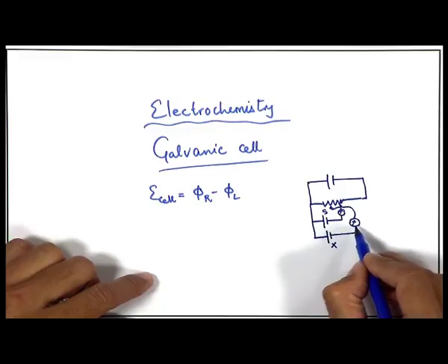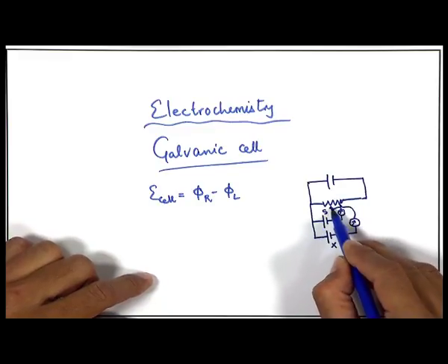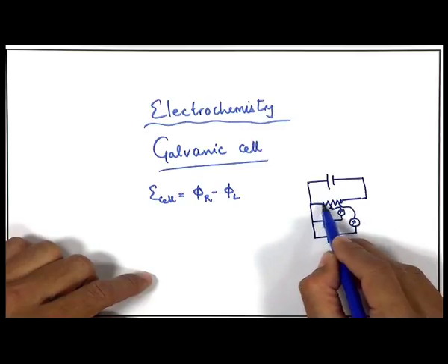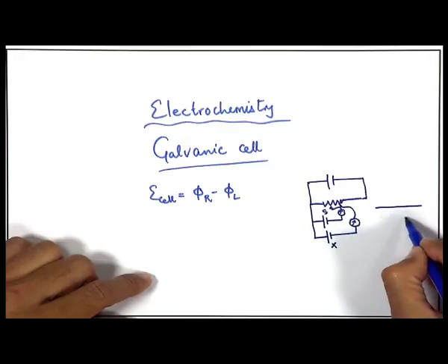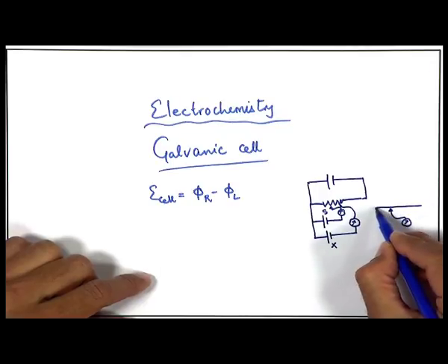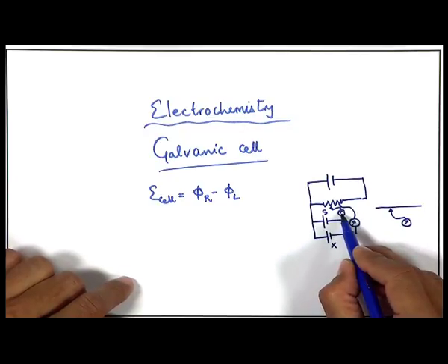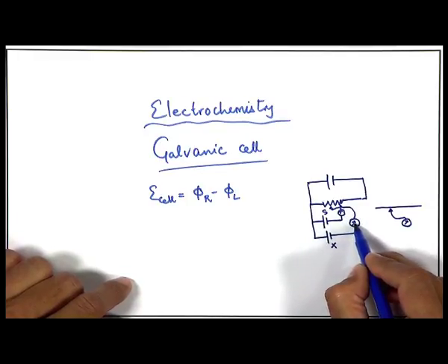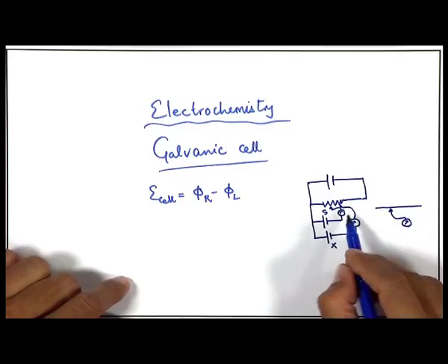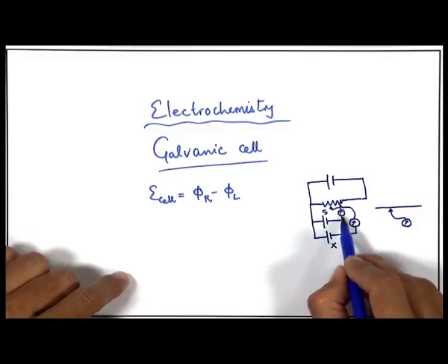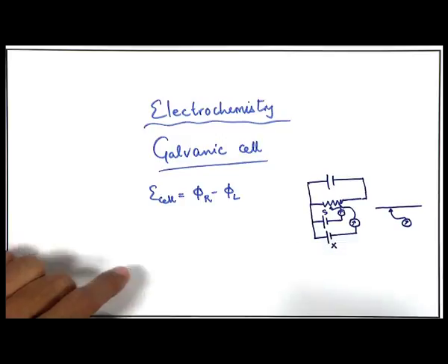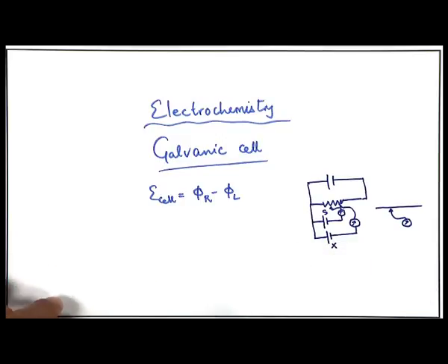So, whenever there is no deflection at a certain point in this resistance, it is basically a long wire, and then you are connecting with one wire where this galvanometer is connected. So, this is generally nichrome or similar wire. So, when this one has no deflection and this one has no deflection, then the corresponding lengths will be proportional to the potential difference or EMF of this cell, and then taking the ratio you can find out this cell potential.